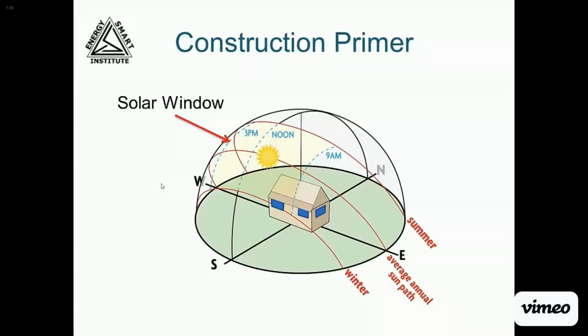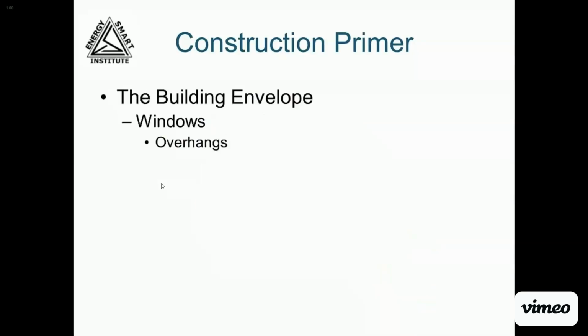In the summer, some type of exterior shading, perhaps from trees, lattice work, or shutters, is critical if the goal is to keep the heat out. The windows on the north side of the house will not have any direct sunlight strike them. These windows should be minimized so the envelope can be fully insulated on the north side. Window overhangs are a major building science consideration.